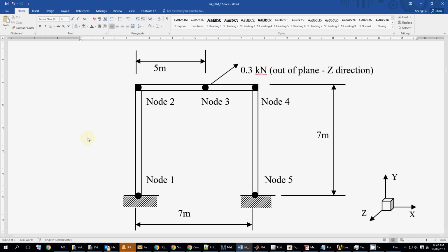So I'm making this video to show you how to build a simple model using ANSYS, and this is the model we want to build. Basically a door frame shape with five nodes and 4 beam elements, and what we want is the horizontal beams and the vertical beams to have different cross sections, and we want to have a force applied later on this node on the beam.